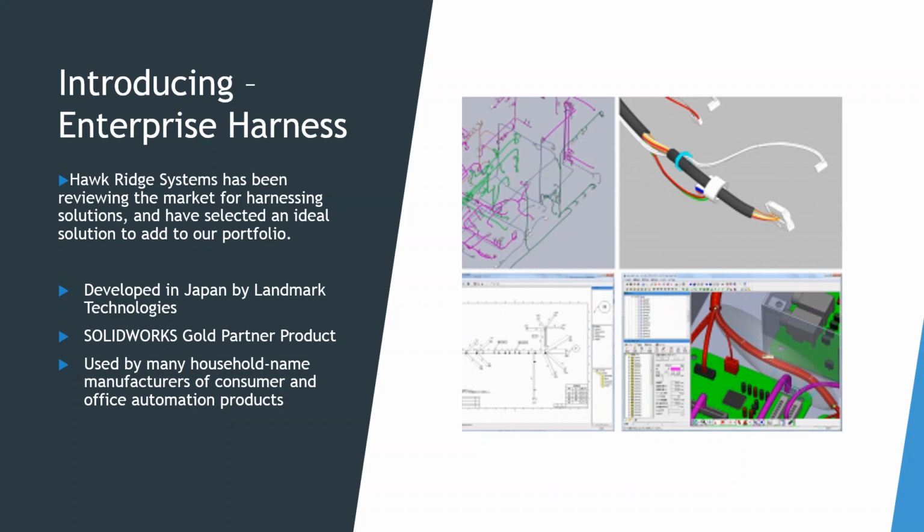Right. You have your automated pin tables, connector tables, lay it out on the sheet exactly as you need, all those great things for building that manufacturing drawing. And because it's database driven and electrical, if something changes, if you go to a different connector, that drawing will be able to be updated. But the one thing we're missing is the ability to estimate length, right? We don't yet know in that environment how things are going to be laid out in 3D space. And to do that, we need to go to 3D.